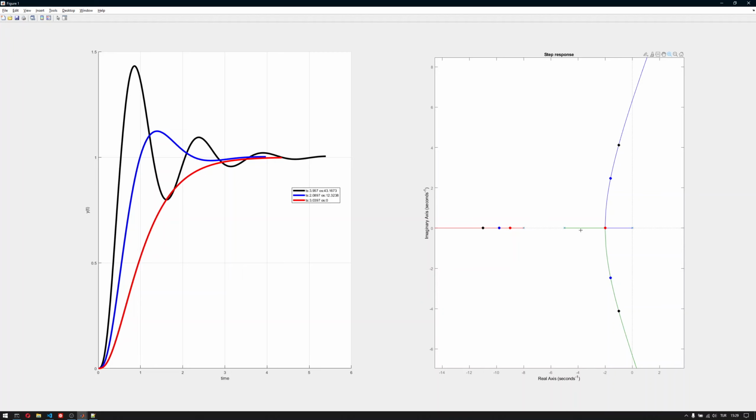So the point where we had the critically damped solution was actually the limit, because then one of them gets slower and slower and the other one is just getting faster, or they move to the right and to the left, and at some point one of them is at this point and one of them has crossed the j omega axis. It is on the right half plane. It's not a stable solution anymore, so therefore we are not able to use it.